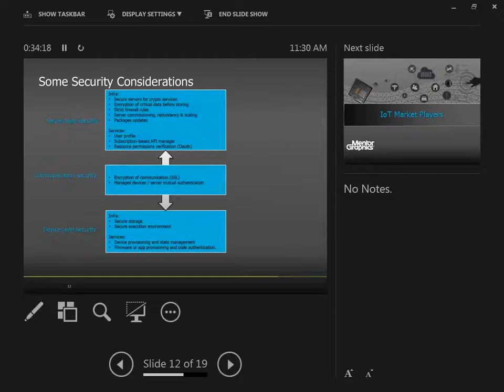Usually this is implemented in the form of a secure element, which is a special microcontroller with tamper-proof security. In addition to the secure element, the device needs special security-related services and needs to be able to follow a proper provisioning flow.